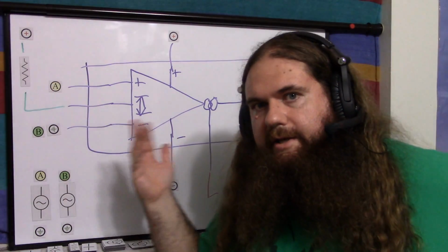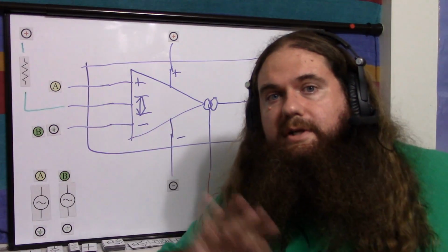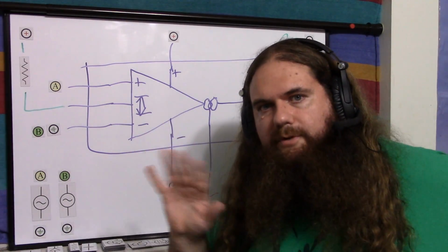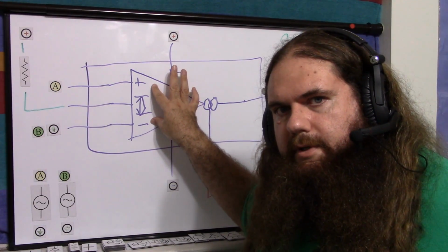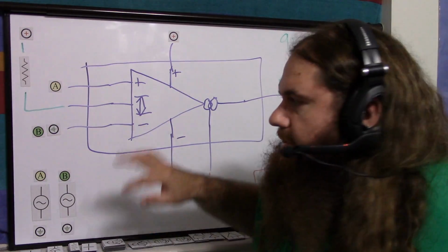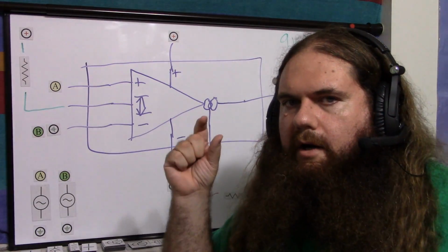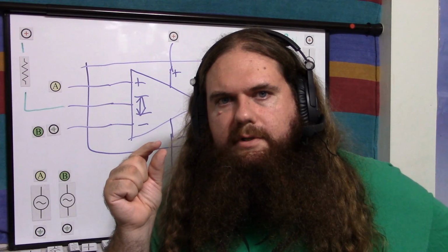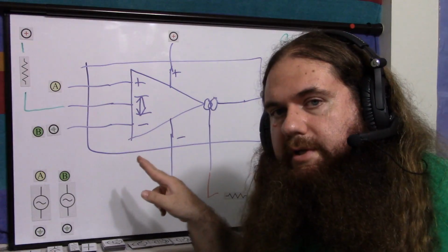And as usual, it's taken me forever to explain this, but I'm going into extreme detail so it's completely clear. So now time for a very quick summary. Your positive and negative differential inputs, your non-inverting and your inverting inputs, are the same as an op-amp. It's non-inverting minus inverting is the differential input. Your op-amp will automatically make the differential input very close to 0: 10, 20, 40, 80 millivolts. For the OTA, it does not.